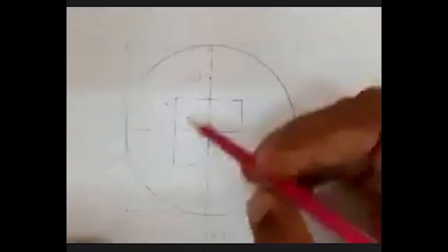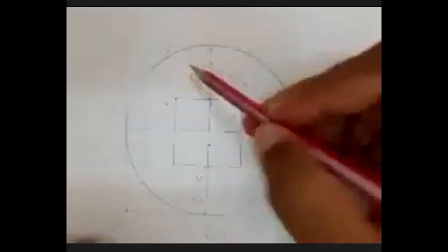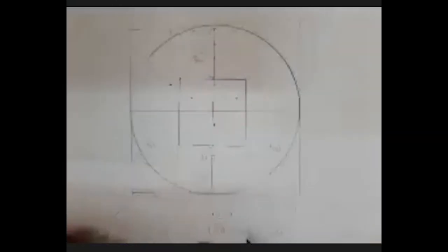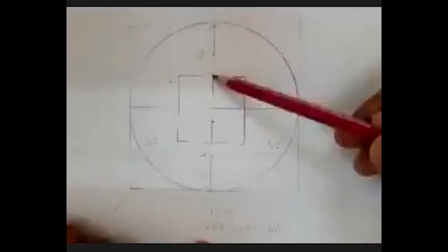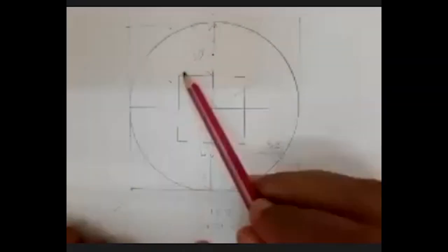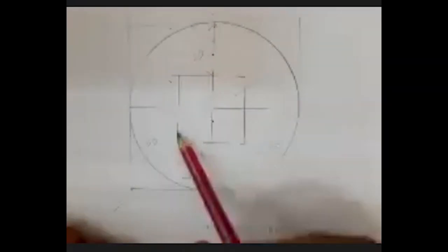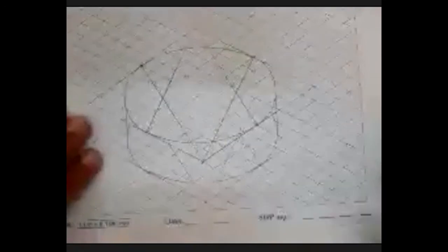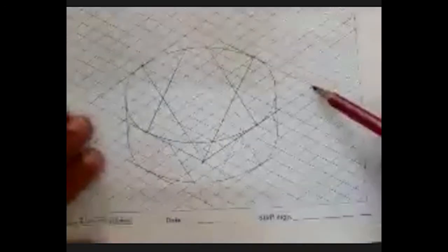That means if from this whole rectangle of 100 mm I leave 30 from here, 30 from here, 30 from here, and 30 from here, I'll directly get a square of 40 mm. So the same thing I'm going to draw here. I have a square block. From here, I'm going to leave 30.